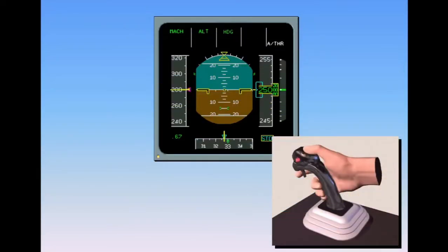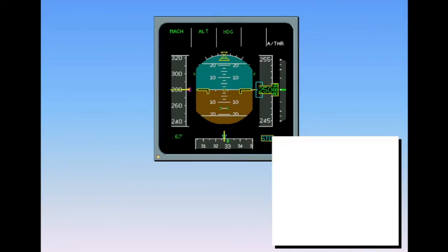In flight mode, if you wish to execute, for example, a left turn, you set the required attitude and then return the side stick to neutral. The neutral side stick position demands 0 rates of pitch and roll. The flight control computers will maintain the set attitude until you use the side stick to demand an attitude change. Throughout the maneuver, there are no pilot trim inputs.